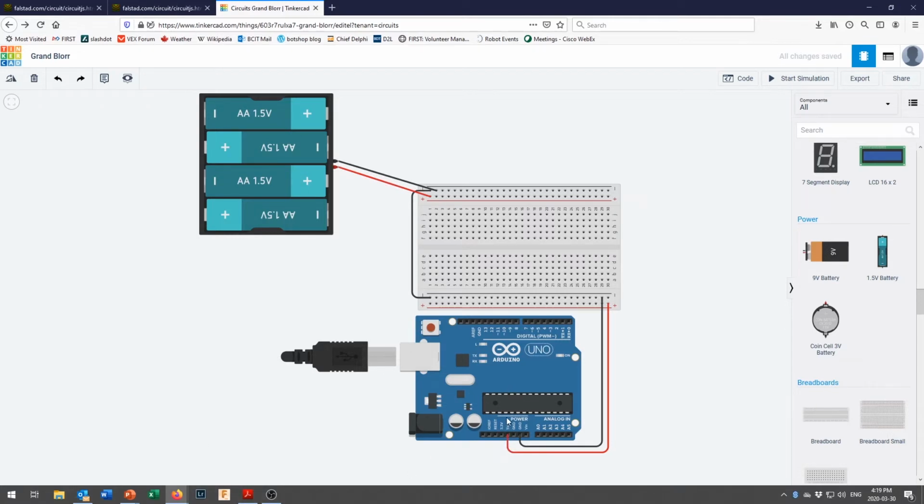And down here, we've got your Arduino's power supply coming in right here that's going to give us 5 volts right along here, but probably not more than about 500 milliamps, because if you're running this Arduino off of your USB port, most computer USB ports are limited to supplying about 500 milliamps. USB chargers can deliver more than 500 milliamps, in some cases up to 2 amps, or even 3 in some extreme cases for tablets and things like that. But we don't want to run that much power through the Arduino when we can run it directly from the battery pack.